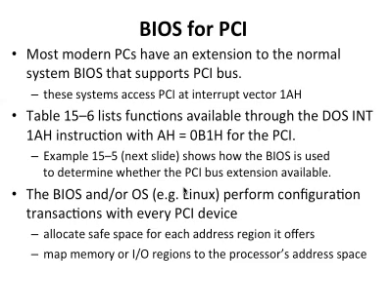The BIOS, in combination with the operating system, will perform the configuration transactions with every PCI device. The purpose of their work in this stage is to allow safe space allocation for each of these devices. Also, it will map the memory or I/O regions to the processor's address space.